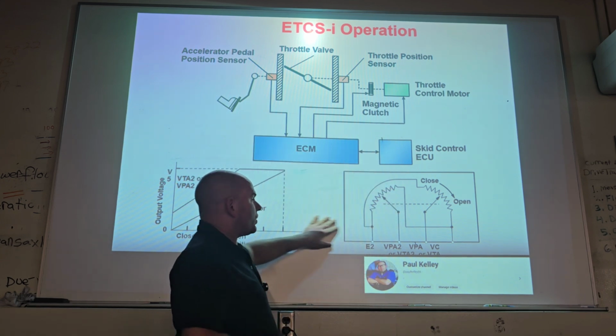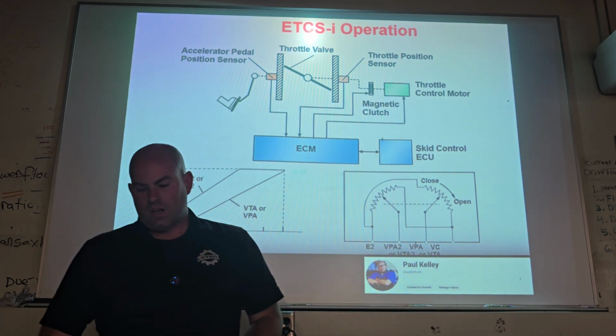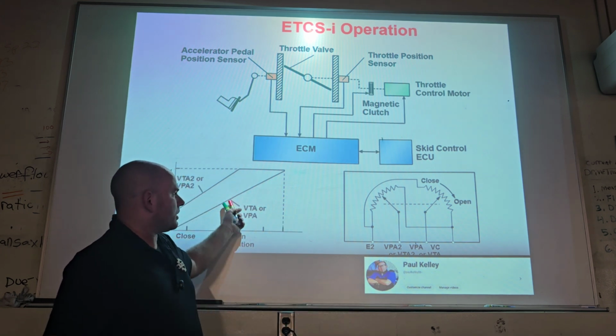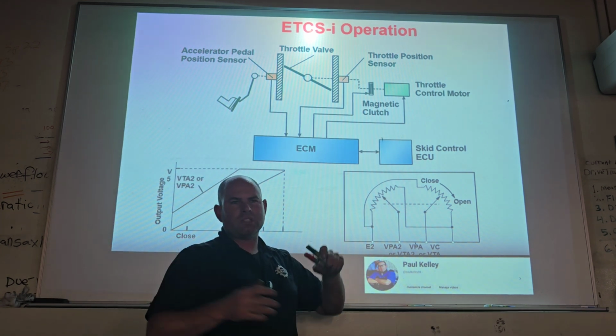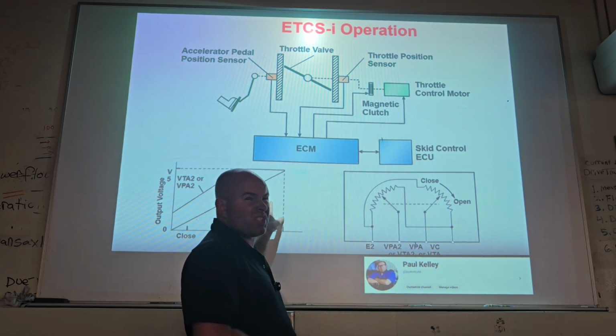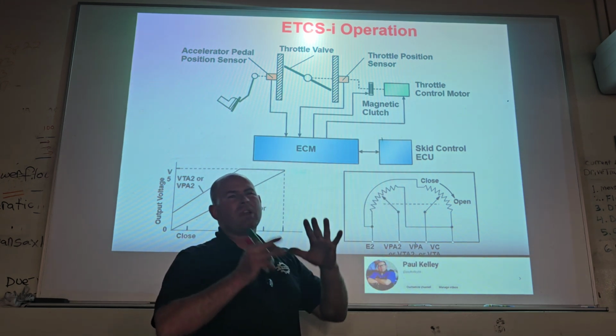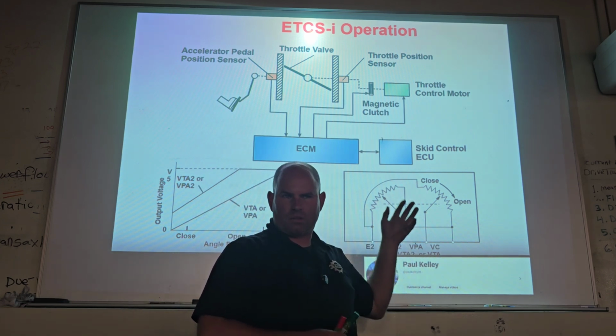Make sense? The chances of it being an electrical fault making it accelerate on its own, I just don't think so. The chances of this causing a transmission issue, yeah, maybe, but that's why we're checking codes. If you have some sort of throttle position correlation, you're fixing that. Do not start trying to put a transmission in the vehicle. Don't. You've got to fix all the throttle stuff.